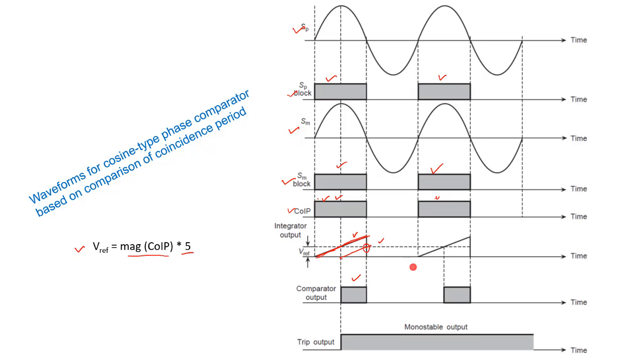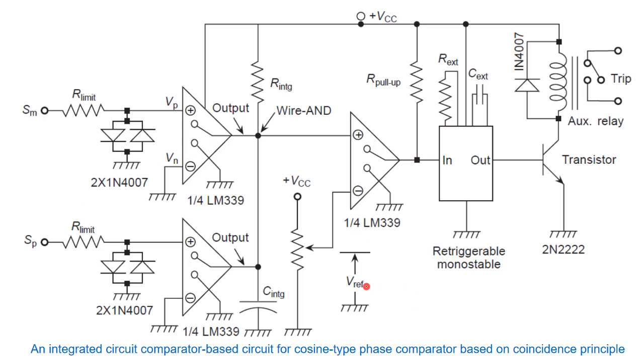We can observe this, then just do it as homework, and you can observe it. Now, when your comparator output has some positive value or some pulses, we can get the monostable output by passing it through the triggering circuit, right. It is very easy to implement.